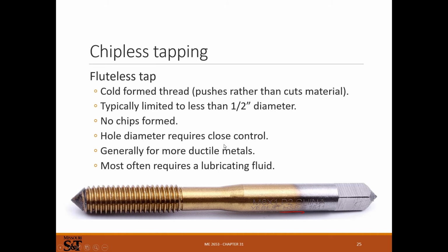Hole diameter needs to be very precisely controlled. You're talking about ductile materials. This might work for aluminum. I imagine you're going to break a lot of these trying to figure it out. Yeah, you're going to need some kind of cutting oil for this, I guarantee it. I've never seen this done, so I can't provide any input on whether it works or not. But for some softer materials, it might work pretty well.